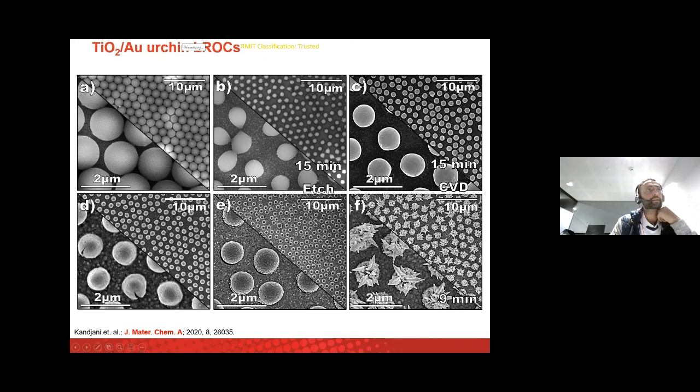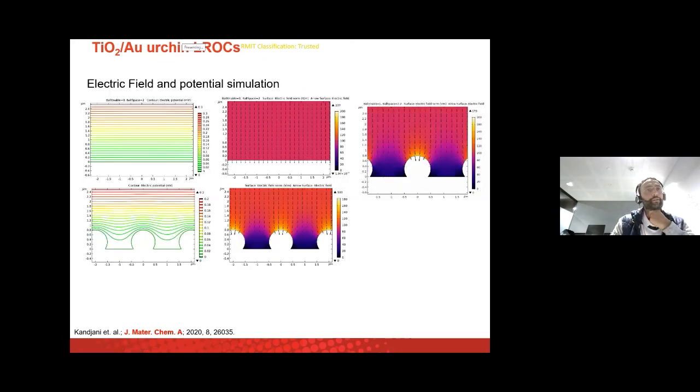So why was this happening? We went to Chris Harrison, who's there, and said, can you model this for us, the electric field, and tell us why this is actually happening? So we compared simulation between a thin film, which you see on the top left, looking at the electric field and also the voltage, and we see that once you go into a colloidal structure, your electric field is actually concentrated on the tip of these colloids. So that's why when you do electrodeposition with a constant voltage, you get your...